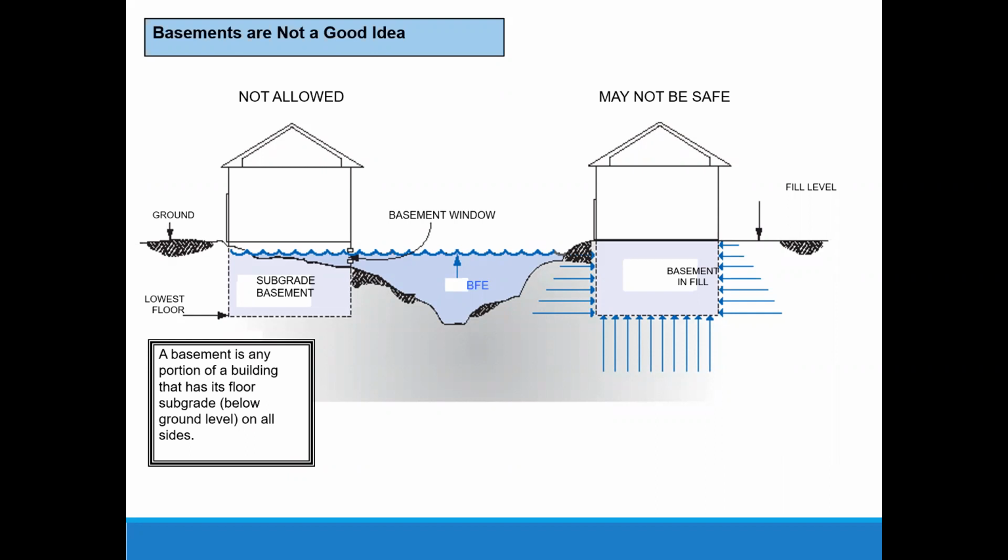Basically, foundation walls breaking is a pretty devastating event for a structure. It's expensive to fix. Back when Steve was a floodplain administrator, and before that, he had a construction job where they would go in and fix basements that had this happen to them. They have to take out a lot of the wall and floor, and then they would have to pour new walls and floors and smooth it out and put in reinforced rebar and stuff. So that's why we don't allow it.